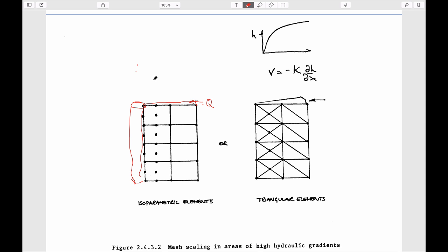And so since by Darcy's law, Q equals the cross-sectional area times hydraulic conductivity times the change in head with radius, this area here changes as you get relatively small here and relatively large here. And so since the only thing that's changing other than the area can be the gradient, then by definition the gradient has to get sharper, steeper as it gets closer. So you'd expect the gradient to look something like this as you went progressively further away from the wellbore. And so these relatively steep gradients are something that you might want to pick up by having